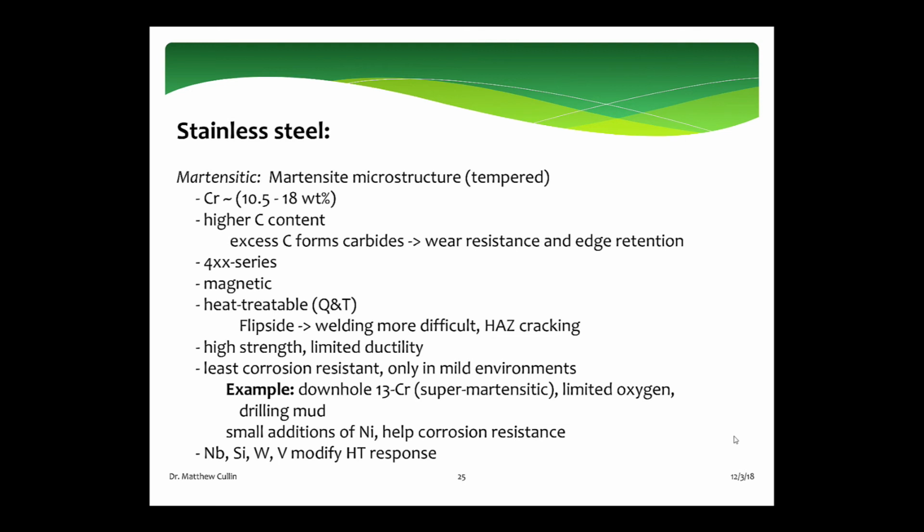So we're talking about oil and gas, right? A lot of the tubulars, a lot of the tubing and casing that we use underground when we're drilling wells, is made of 13 chrome, which is a super martensitic stainless steel. And you might say, well, isn't that a really corrosive environment? Well, not really. If you think about it, down in a reservoir underground there's not that much oxygen.